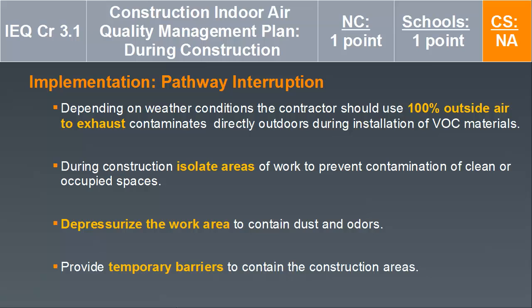During construction, you want to isolate areas of work to prevent contamination of clean or occupied areas, or else that gypsum wallboard or carpets will absorb those contaminants and then emit those when the building is occupied. So you want to depressurize the work area to contain dust and odors, and provide temporary barriers to contain the construction areas.